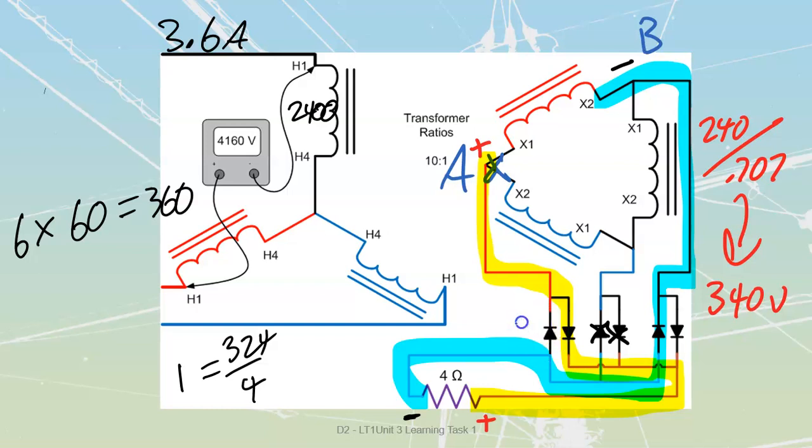The average value of current that's traveling through here, we see that my current, all 81 amps, which we calculated before, is traveling through this diode as well as through this diode. It's a series circuit that is basically diode, load, another diode is what we're always going to be going through. So each pair of diodes is going to spend a little bit of time conducting, then the next pair of diodes is going to spend a bit of time conducting, and the next pair of diodes is going to spend a little bit of time conducting. So each one of them is once again going to carry a third as being their average value.